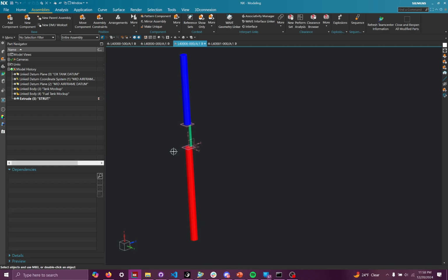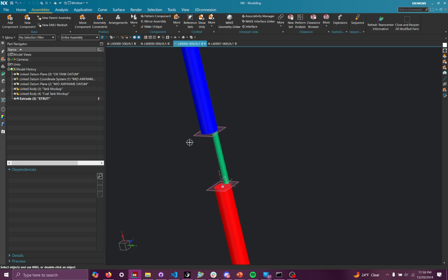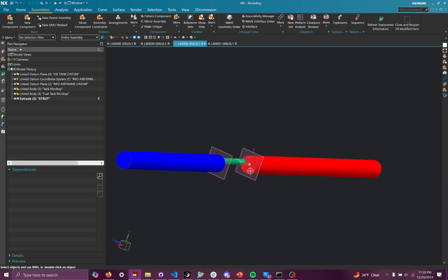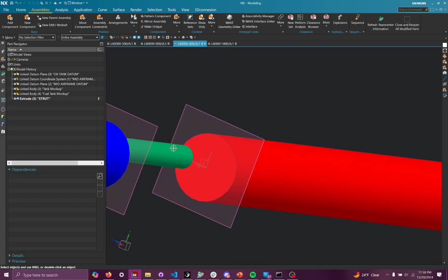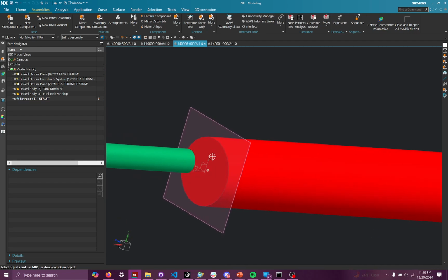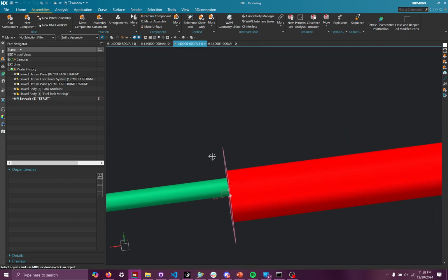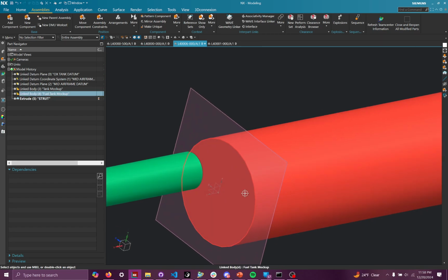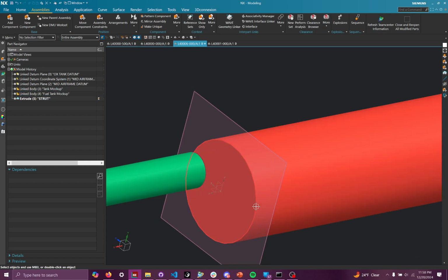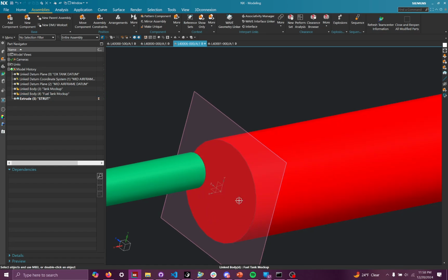Why they're there is a pretty intuitive answer, I hope. Imagine that there is some kind of bulkhead feature here, or bulkhead part. Right now it's just a cylinder, but you can imagine that there would be some kind of pad with a bolt pattern used to connect with a strut. And you'd have three of them along the circumference of this tank.